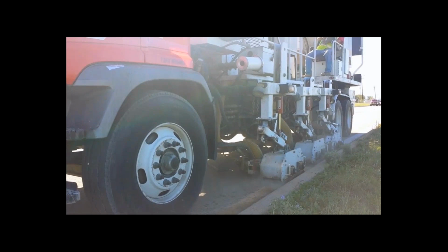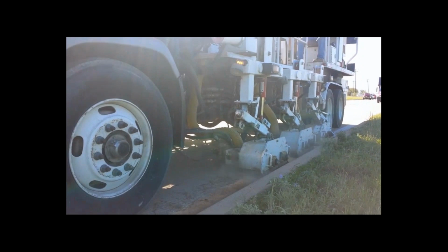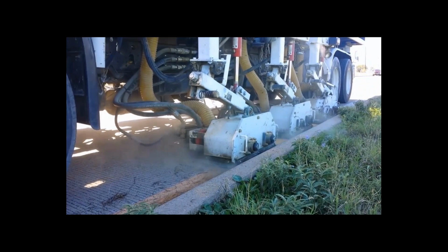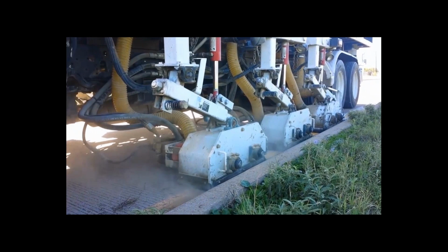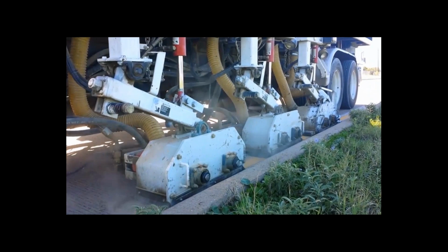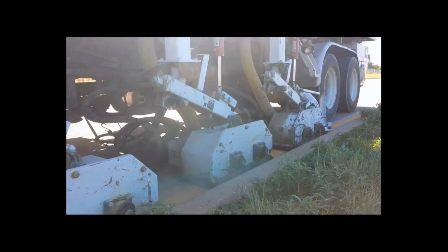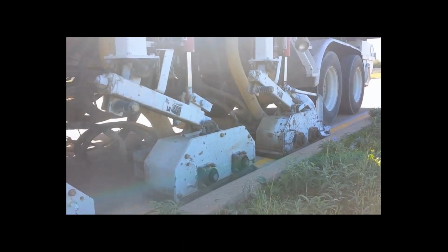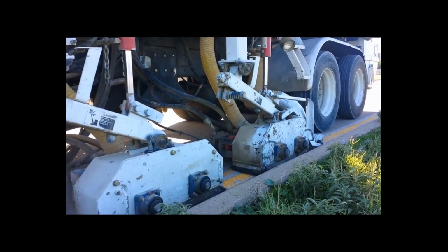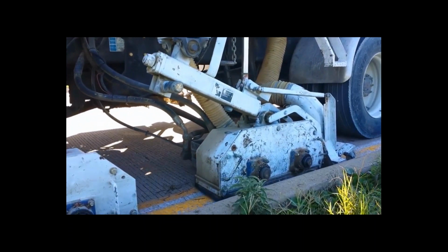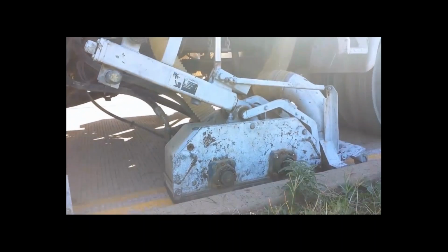I'm going to show two videos. This one right here is a picture of a grinding truck, because typically sometimes we don't always groove everything. We're going to remove the existing pavement marking. And here's an example of the grinding truck. You can see that it's not 100% removal, and you can also see that it's causing some damage to the concrete pavement it's on.